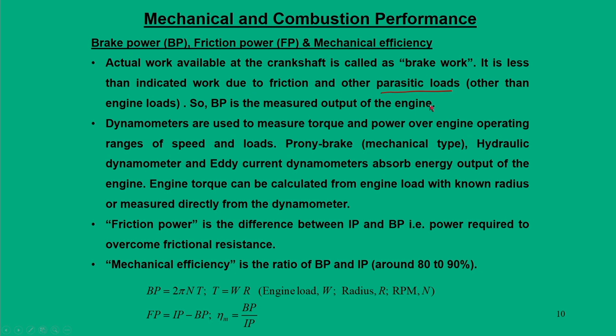Now, how do we measure this brake power? For that purpose dynamometers are used. So, what does the dynamometer do? They measure the torque, because the engine is run at a certain RPM. We can run the engine at different speeds and loads, that is our input end, and these dynamometers measure the torque, and then from the torque and engine RPM we can calculate the power.